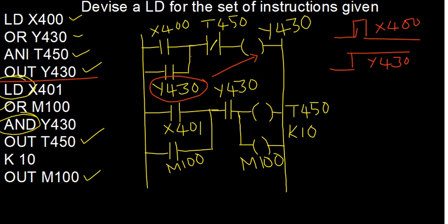So now you have got X401 in the next rung. X401 is in parallel with your M100. For the time being, let us not worry what exactly is the position of M100, because I have to go across one or two more elements in that second rung. So now, let us say that I close X400 somewhere here. That means this is the output here.